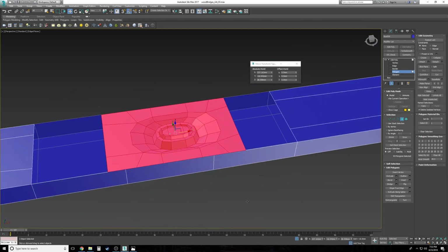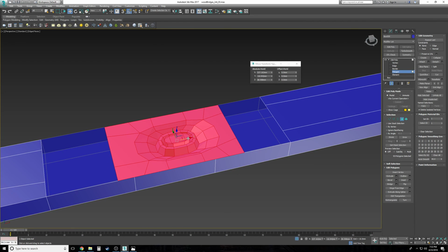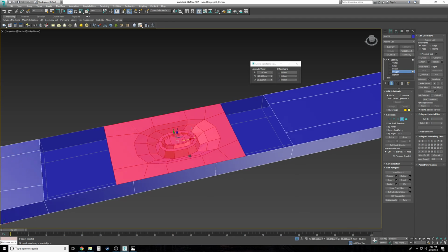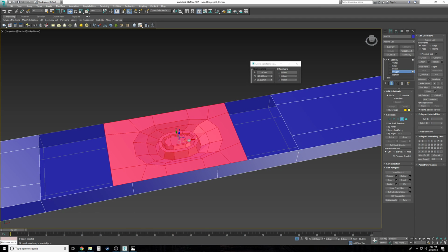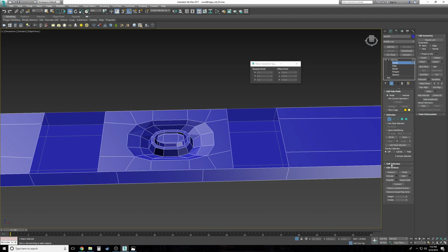Isolate this bad boy so we just have this plank here. Now this piece, this red piece here, is not joined with anything, but it is attached to the plank as being an object. But we haven't fused anything together. But we have just enough resources here. We can basically fuse everything we want to, because there's the same number of polys everywhere. So we go to target weld and go to town. Just on the top, because that's all that matters. Go all the way around.